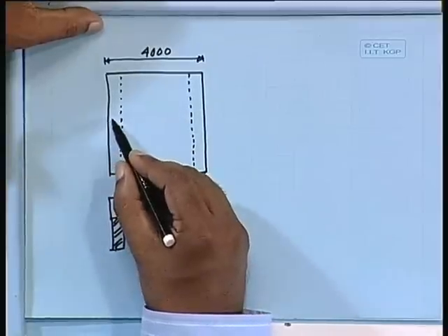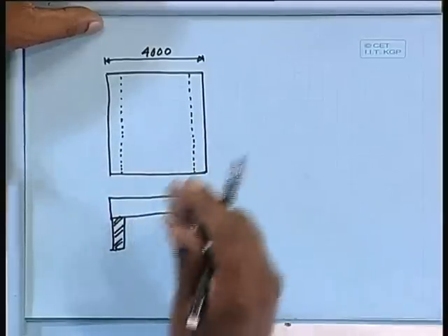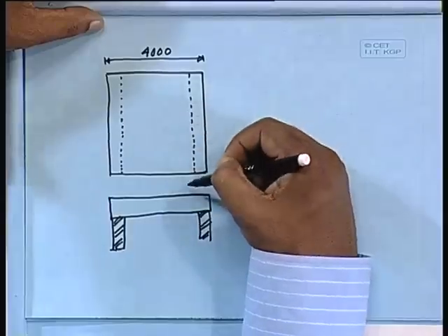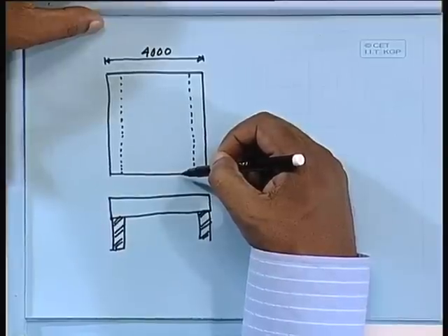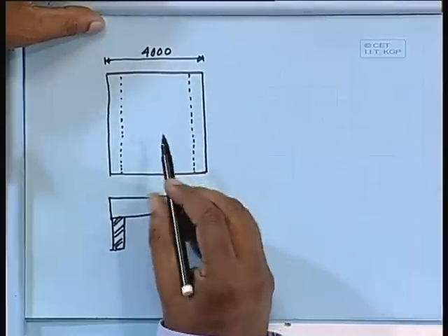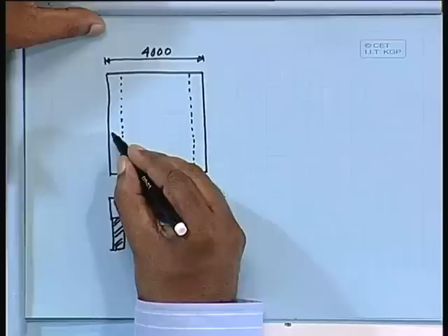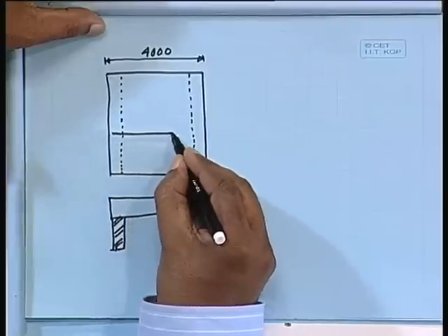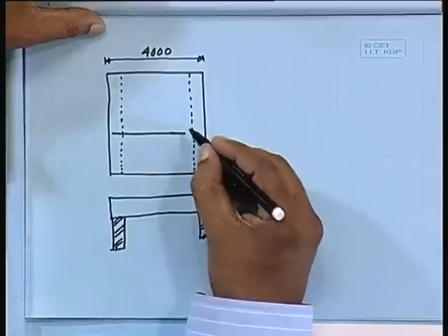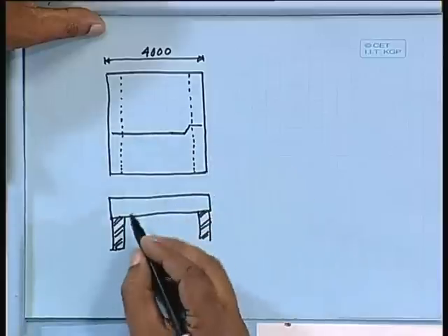What we shall do, we can just simply provide the reinforcement, say just one horizontal line, but we have to provide the reinforcement at the bottom as well as at the top. So, in the support also, we shall provide certain nominal reinforcement. Let us start, this is the one we are starting here, one bar, and then it will be cranked and go up like this.